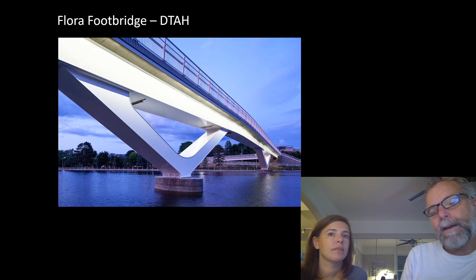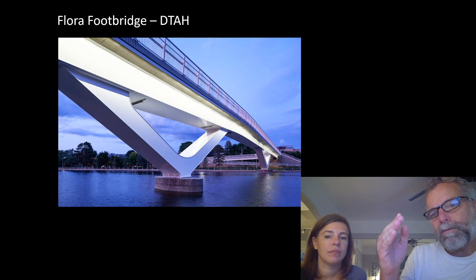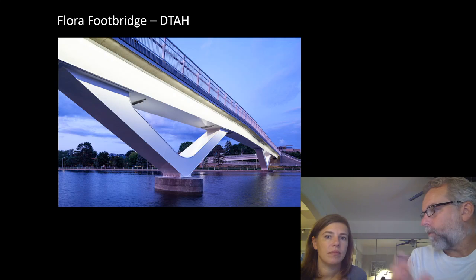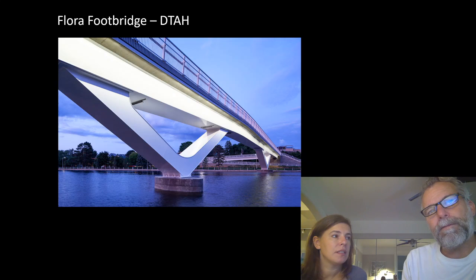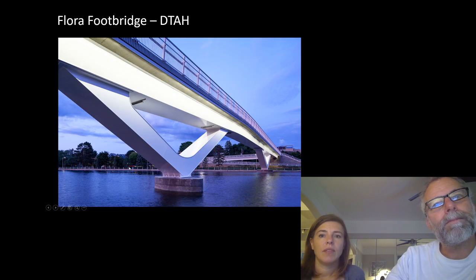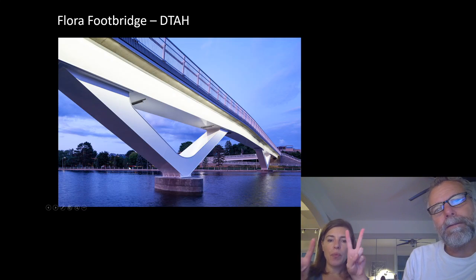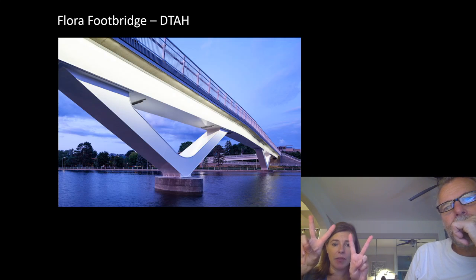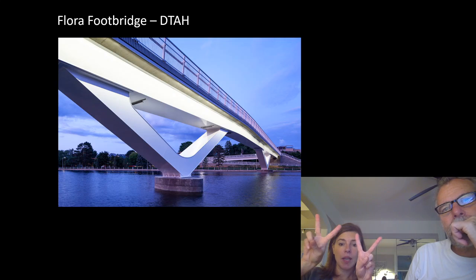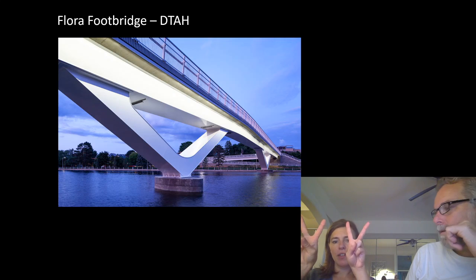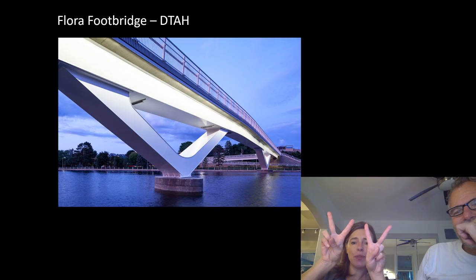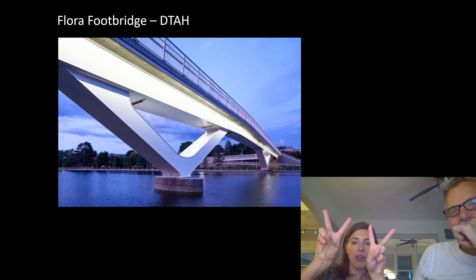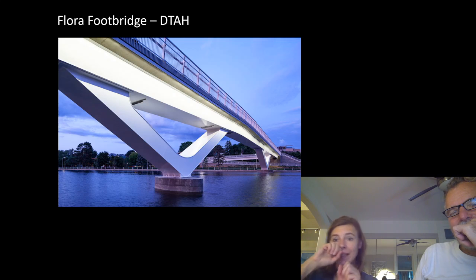This is a painted bridge. Paint is most vulnerable on the sharp corners, and they probably had to grind all of the corners to about a 3 millimeter radius. All the welds would have been continuous as well, rather than stitch welds. So these are built up on 2 V's that you can imagine aren't stable by themselves, but they're great for supporting loads. But because we have 2 of them, they're starting to balance each other. They become a braced system where they're balancing each other out.